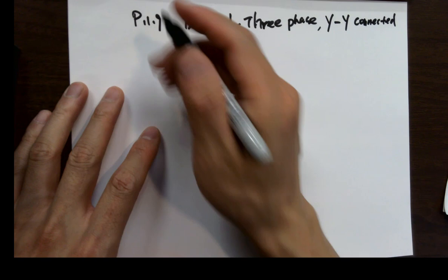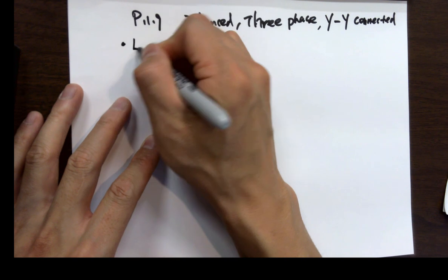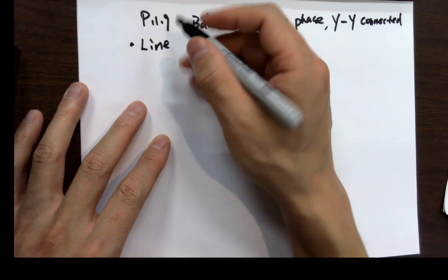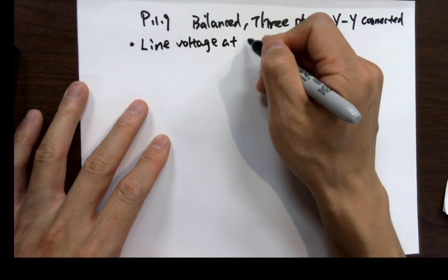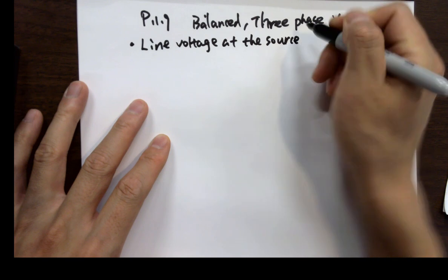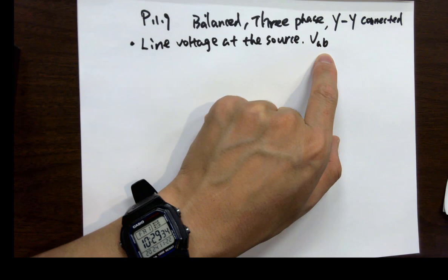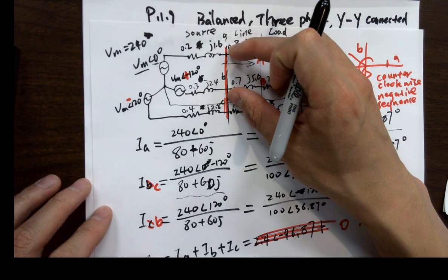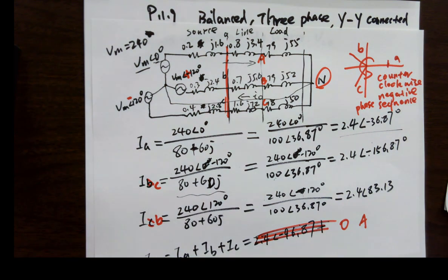And what is given, so this starts getting confusing, okay? I cannot skip every single word here because it makes a difference. The line voltage at the source is VAB. If it shows you VAB, you know that it's a source terminal voltage between these 2 nodes, right behind the source impedance. Remember, all the YY connected 3-phase systems are labeled in the same way.